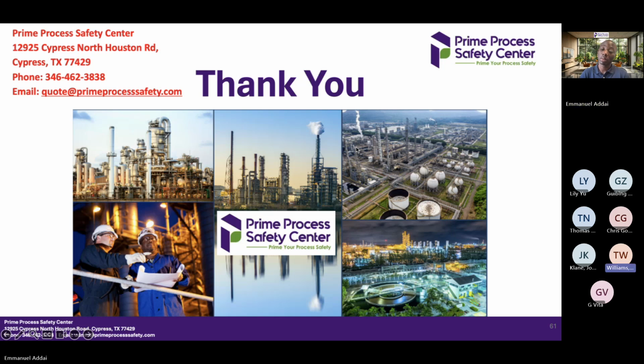Thank you. And a follow-up question is guidance on handling the marginally explosible dusts, the ones that often come back with a weak explosion, with a Kst in the 40 to 50 range on the standard go-no-go test. My understanding is that on the standard go-no-go test in the 20-liter sphere, you can get false positives on them. So it's very tempting for employers to hope that they're not explosible if they get tested under the gold standard 1 meter cube sphere.